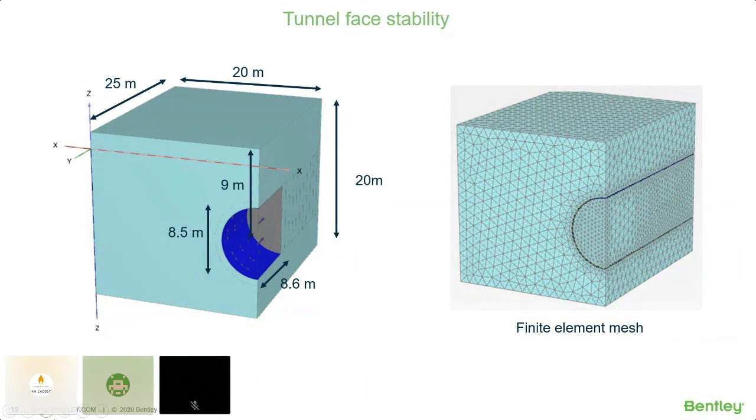Too low a pressure at the tunnel face can lead to an inward collapse of the tunnel face, which we call the active failure case. If you apply too high a pressure, that can lead to a blowout at the tunnel heading, which will be the case of passive failure. Because of either a very low or a very high pressure, this could lead to a large deformation at the ground surface.